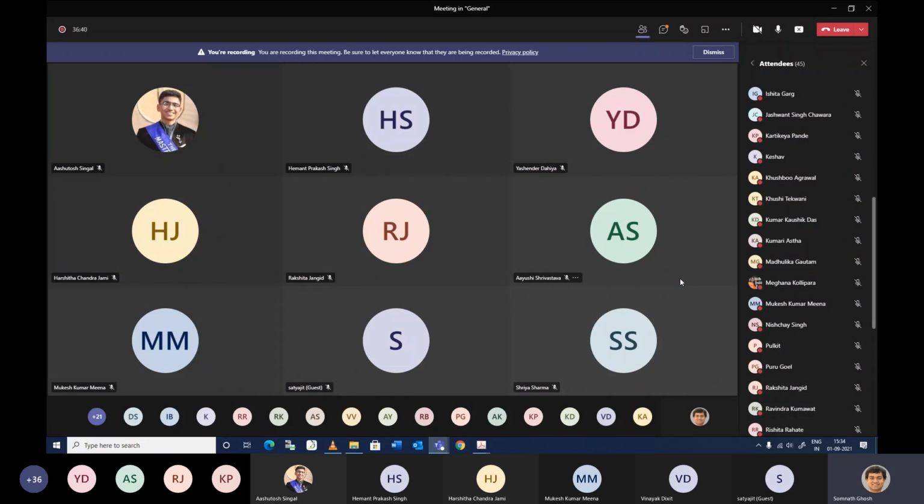Also provide the graphs wherever possible: the energy at different points, and the velocity as well as the pressure. Then you can compare what is changing, or if at all it is changing, because for the derivation of Bernoulli's equation, the main assumption is that there are no external losses due to friction or any other thing. Whether it is fulfilling or not, and if not, then why it is not fulfilling. Okay, so that's all from my side.